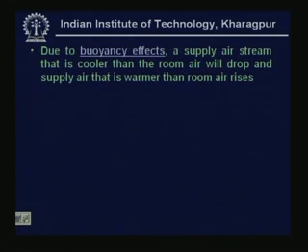So, what is buoyancy effect? As you know, buoyancy effect is a result of temperature gradient which leads to density differences. Because of the density differences there will be fluid flow. Due to buoyancy effects a supply air stream that is cooler than the room air will drop and supply air that is warmer than the room air rises. That means when you are supplying cold air to the room, because cold air is heavier than the warm air, the cold air will tend to drop. Whereas, if you are supplying air that is warmer than the room air, then because of the buoyancy the warm air tends to rise. We know this from our basic physics.